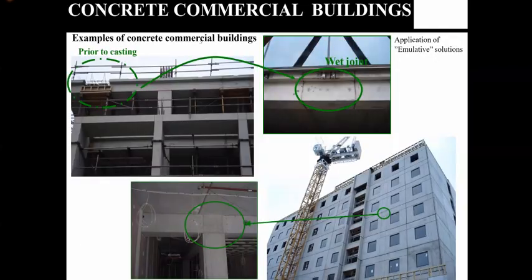When it comes to concrete buildings, the majority are precast concrete buildings, where you have precast elements and they are joined using cast in situ elements, right? Now you can see on your left picture a precast beam with a central portion which is a cast in situ joint, right? And finally what you see is a complete monolithic joint, which has a system performance the same as a cast in situ element. The advantage with this is you don't need formwork.